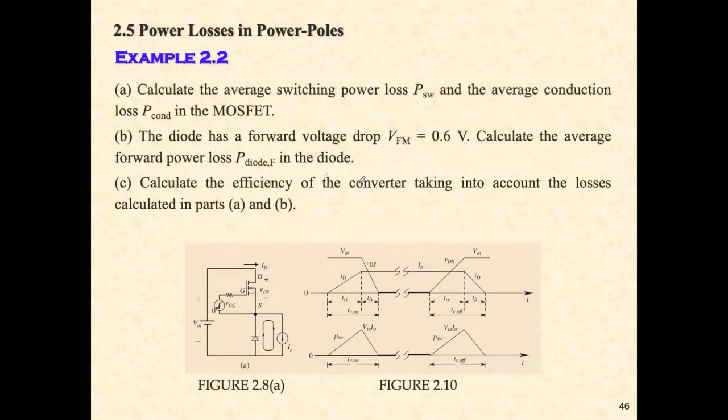Then the question asks you to calculate the average switching power loss P_sw and the average conduction loss in the MOSFET. The time information can help you calculate the switching power loss, and the resistance can help you calculate the conduction loss.